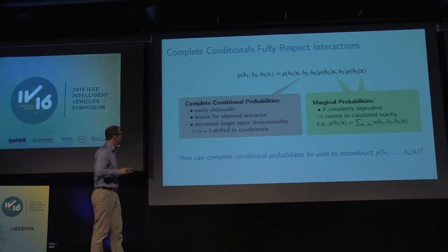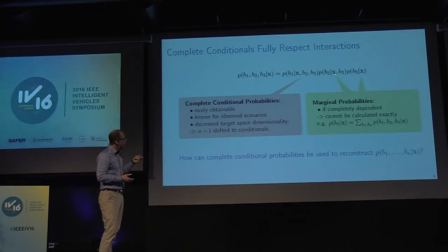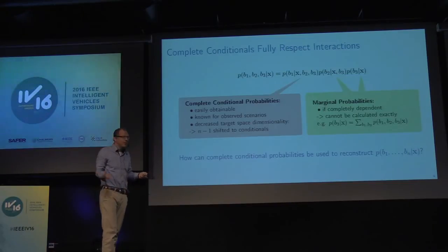So you could call them incomplete or marginal probabilities. And the thing is that learning these probabilities is easier than learning that one, because as input here, you take all the hypotheses of all traffic participants into account, as data. But here, you don't, as you can see from marginalization, input these different maneuvers in learning. These probabilities are dependent on the complete joint. And this you don't have so far because you would like to estimate it, so this is a problem.